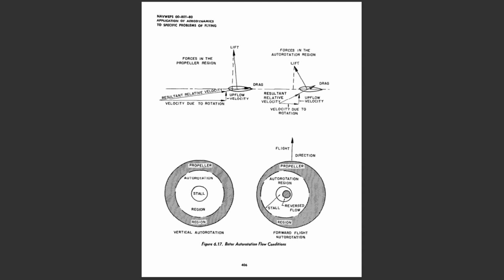In case of engine failure, the fixed-wing airplane will be glided at maximum lift-to-drag ratio to produce maximum glide distance. If minimum rate of descent is desired in power-off flight rather than maximum glide distance, the fixed-wing airplane will be flown at some lower airspeed. Actually, the minimum rate of descent will occur at minimum power required. The helicopter exhibits similar characteristics, but ordinarily the best autorotation speed may be considered that speed that results in the minimum rate of descent rather than maximum glide distance.